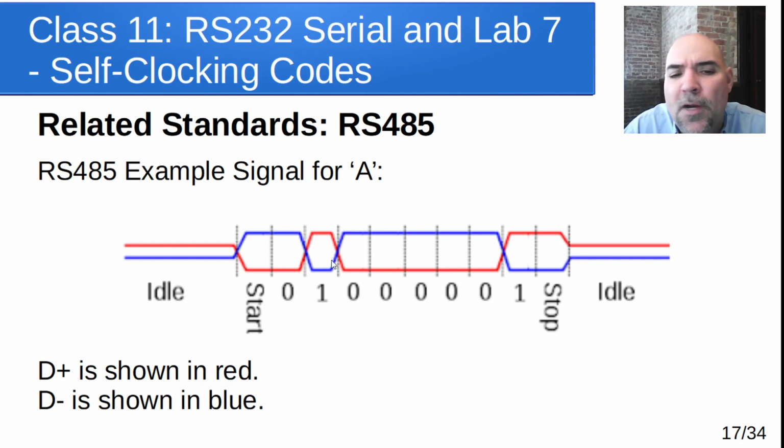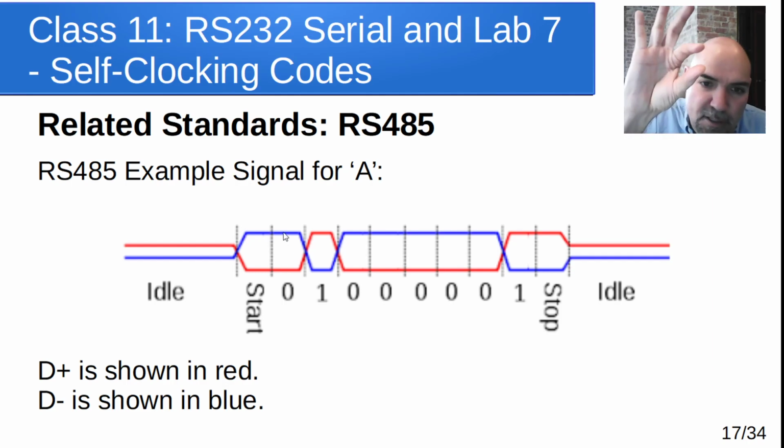And usually these are wired with what's called twisted pair wiring, which is what's inside of an Ethernet cable, if you're used to seeing those. And because of that twisted pair nature of those wires, where they're kind of in a spiral, that makes them very immune to noise. The reason for that is any induced noise would affect both of the wires in the same way. So say a machine turns on and makes a spike, both of these would jump up. But since it's differential, all that matters is the distance between them.